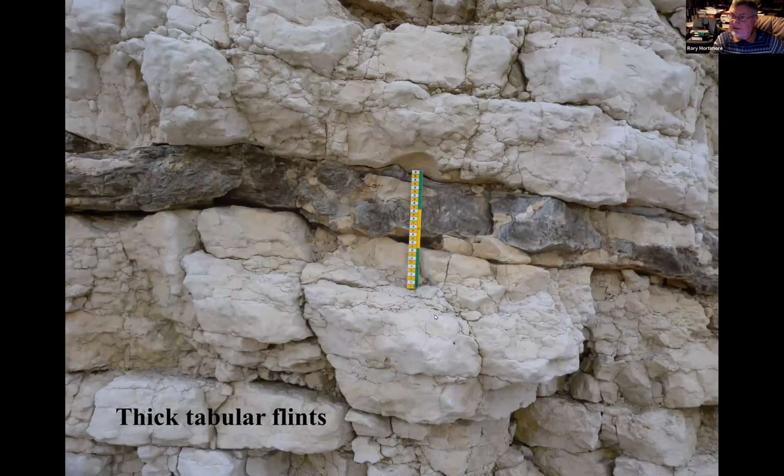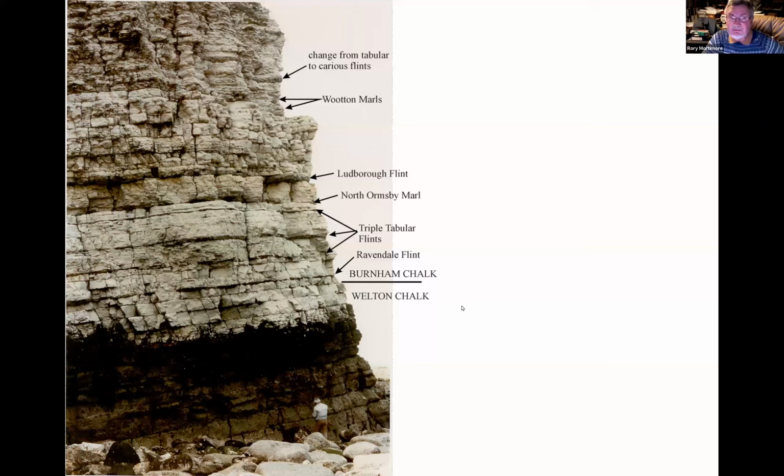So if you're drilling into it, you're going to hit it pretty well everywhere. If you're putting a boring machine in for cables or whatever, that's going to be over a very long distance. You want to avoid those if possible. And we know where they are because we've done enough stratigraphy in the chalk now, studied the chalk sufficiently well, and we've got good logs for all the coastal sections and good logs for the boreholes.